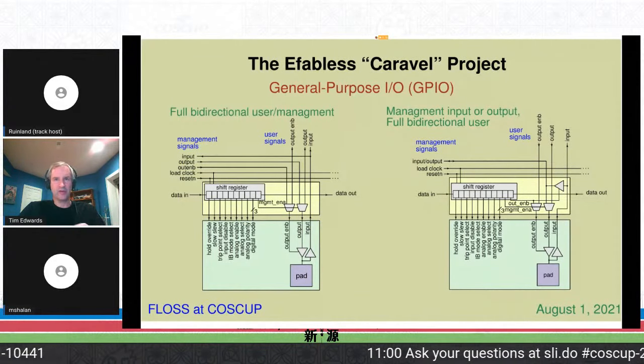The resources that complete the operation of the full chip include a power-on reset circuit and a digital locked loop clock controller. The power-on reset is the first analog component created specifically for the Caravel chip. It monitors the power supply and will generate a reset until the power supply reaches a good value and is stable with an approximately 15 millisecond delay.